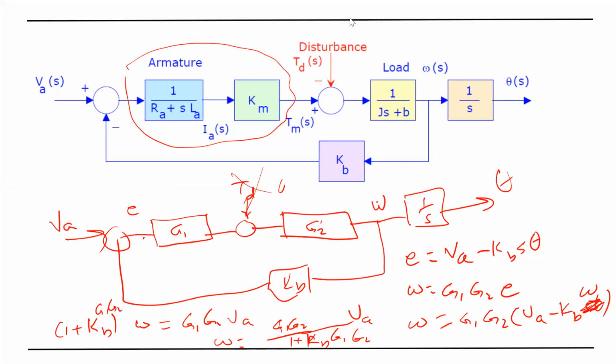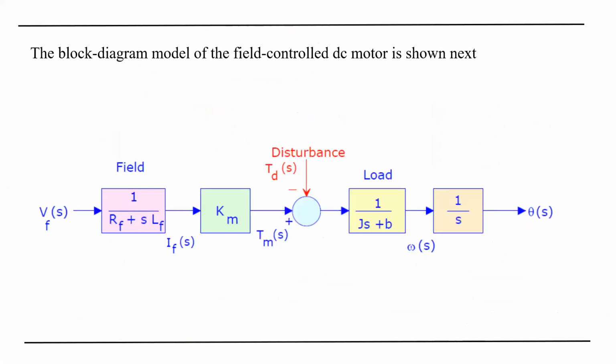I'm trying to show you this can be done either by direct substitution, or later on, when we talk about what we call a feedback loop, we reduce this feedback loop into one block. I see, reduce this to one block and multiply by the other. In the open loop system, the transfer function will be the multiplication of all the blocks. If you have a feedback system, we reduce it into one block and then do the same. But anyway, you don't have to know the feedback.